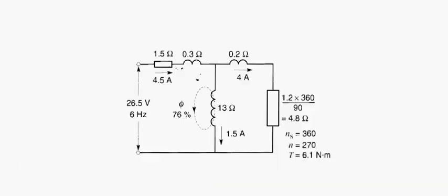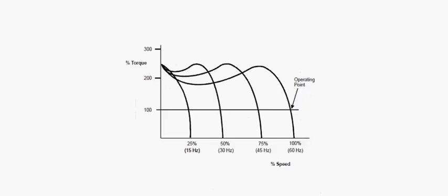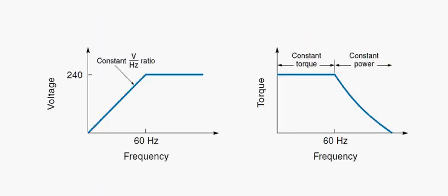What else can we talk about on the boost? I think that is about it on the boost. Now the boost is a nice handy feature to have. Sometimes we might want a little bit more than the nominal voltage, so we'll increase the boost to give more torque at the lower end, because you might have a load that has a high inertia on the load, and you just need to get the load moving.